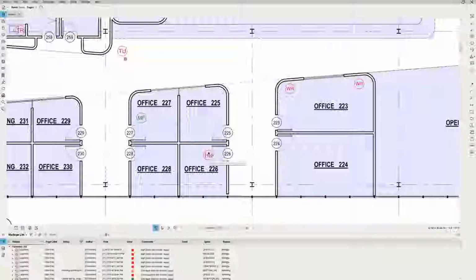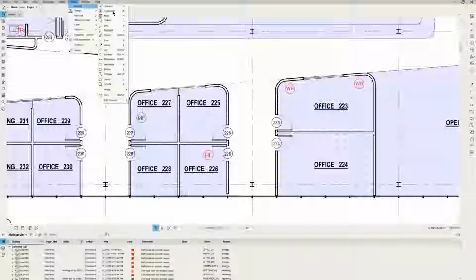So what we're going to do here really follows a workflow. We're going to use a template. Bluebeam has a standard template we could use as a starting point. We're going to modify the form slightly, and then we're going to deal with signatures and how to hyperlink it. So I'm back in this same document that has a lot of work on it, and now we're going to create an RFI, a request for information. That's pretty easy to do here by using the tool markup, and I'm going to use one of my favorites, which is the Cloud Plus.